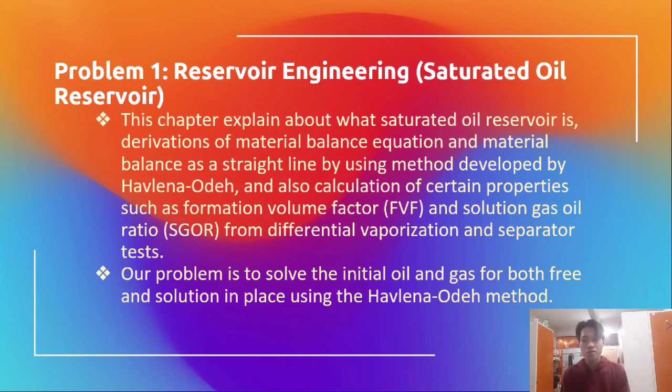The derivation of material balance equations is also explained in this chapter, such as the material balance equation for saturated oil reservoir, Schilthuis's material balance equation, and material balance as a straight line by using a method developed by Havlena and Odeh, and also the calculation of certain properties such as formation volume factor, FVF, and solution gas oil ratio, Rs, from differential evaporation and separator tests.